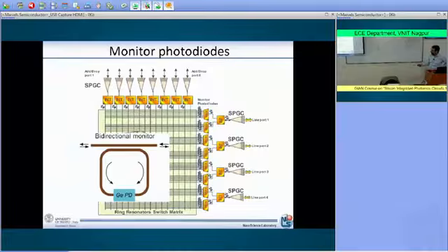The advantage is that on one side you control the coupling, very small coupling, because you do not want to remove too much power from the line. Then you have a looped waveguide so that you can monitor both the signal that is coming from here, is coupled and reaches the photodiode, or the signal that is coming from there, is coupled and reaches the photodiode. So this is a bidirectional monitor of the light propagating at a specific point of the waveguide.